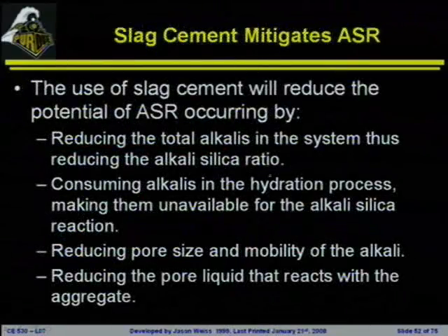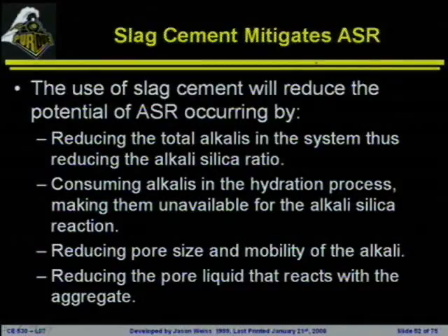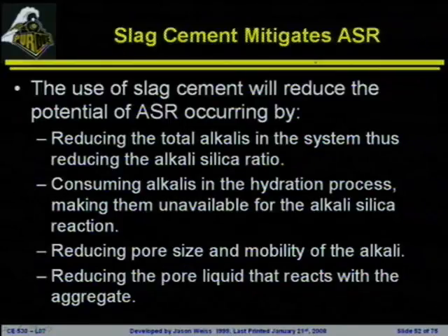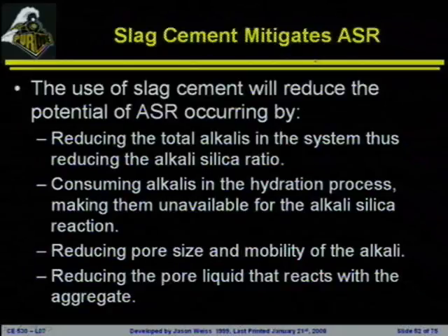As mentioned before, it will help in mitigating alkali-silica reactivity. This is an aggregate that will react with the alkalis that are coming off of the cement. The main idea here is the alkalis will actually react with the slag. They'll actually participate in the reaction, so they'll reduce the overall alkalis, taking them out of the system. They'll also reduce the size of the pores, and they'll make it harder for things to flow through the system.